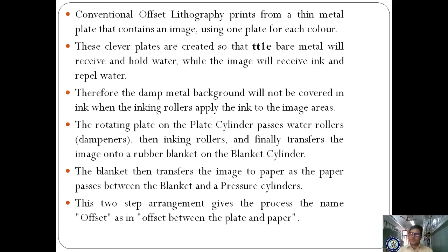Okay, so when the smooth blanket is on that cylinder, and whatever the metal plate is placed, through that metal we have poured some ink and some water. When the water is sprinkled on that plate, the image will be formed. The image will be transferred to the blanket, and the blanket will transfer that image to your paper through the pressure.